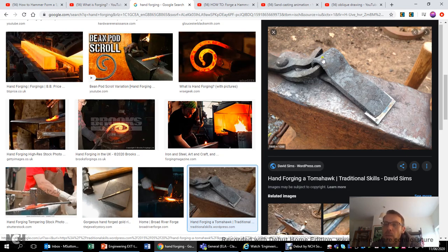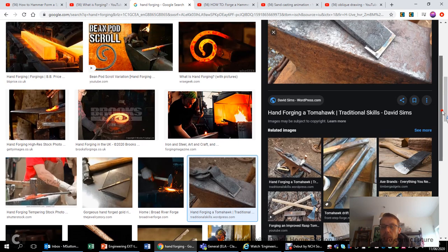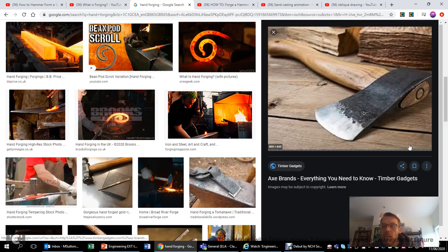This part round here is made from a more malleable metal, which can be easily forged and shaped. And then if you look at this end, we have a harder piece of tool steel. So this is where you've got that slightly higher percentage of carbon coming into the metal, which means that it can keep a blade far better. And this is heated repeatedly. It is obviously hammered into the shape, and then it can also be ground down once it's fused together, because forging can at the same time forge the metal into one piece, and then it produces that axe blade.